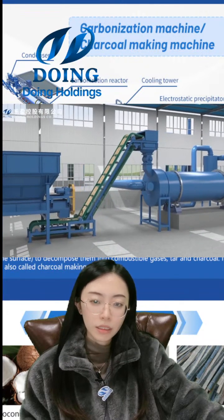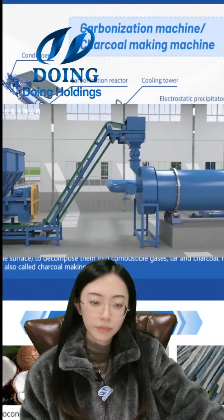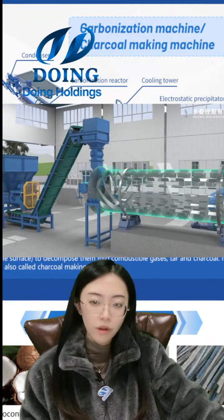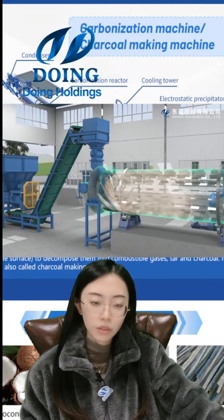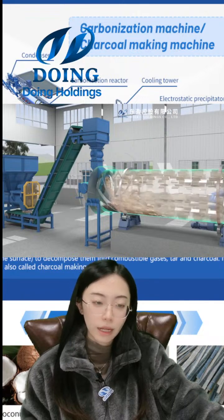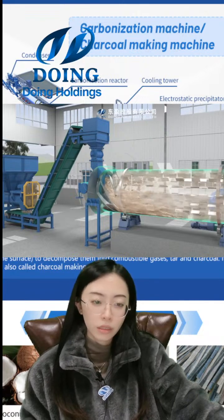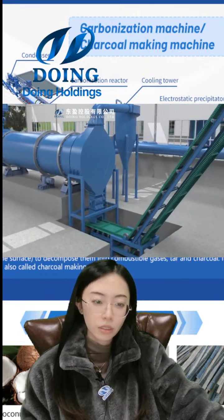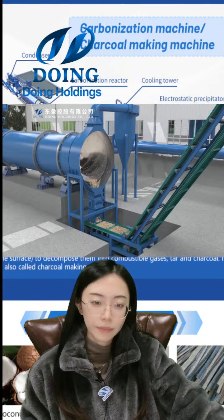And this is the feeding system to feed the raw material into the drying machine and then into the carbonization furnace. The moisture of the raw material going into the furnace is better lowered to 15%.